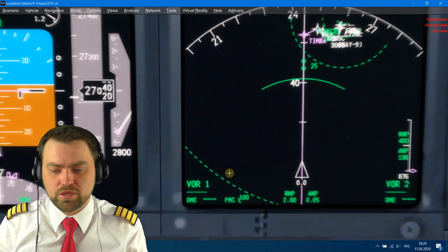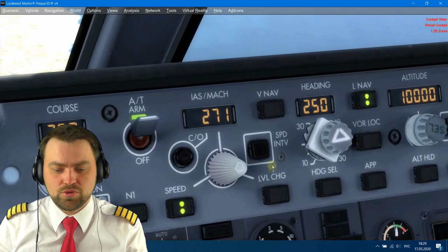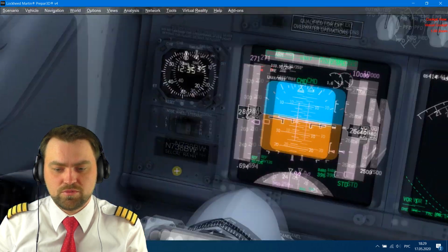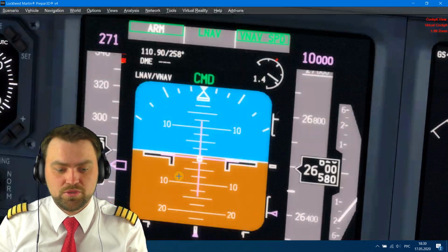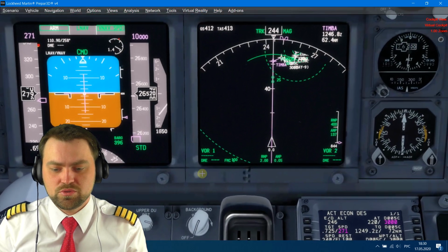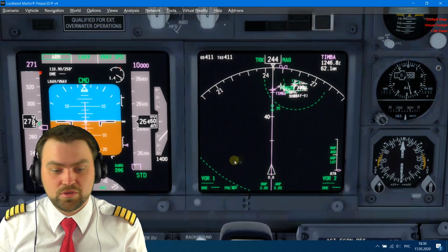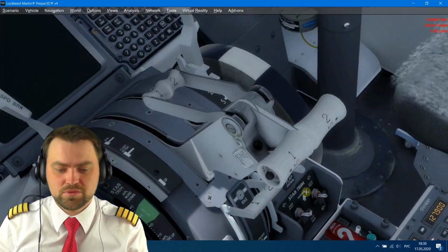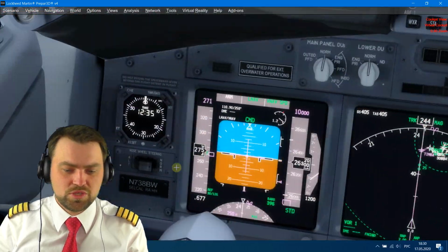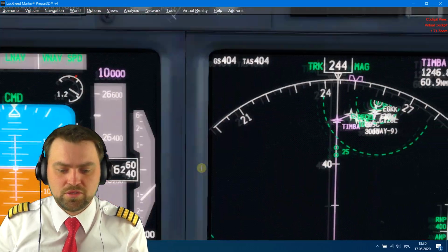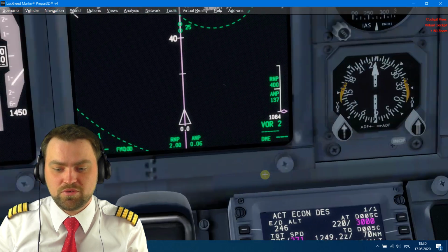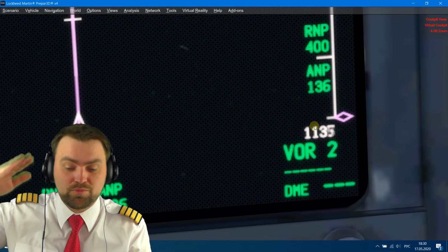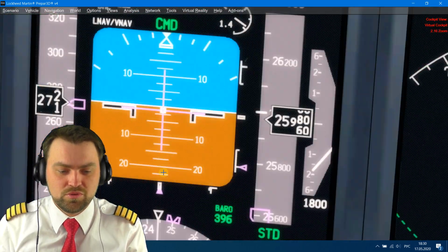But what if the air traffic controller tells you to reduce back to 270 knots and you are above your profile, like here? So you go back to VNAV, you're above the profile and you're in VNAV speed. VNAV now is not maintaining your profile, it's maintaining your speed. So we have idle thrust, your speed is 271, but at this point you're still deviating above the profile. You cannot reach it with your current speed.